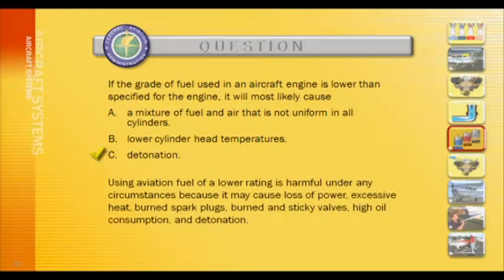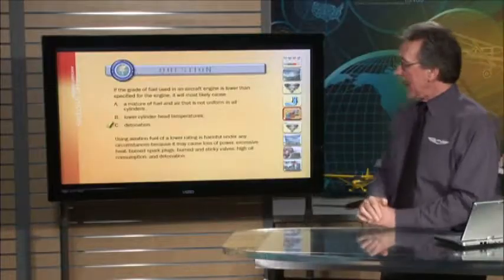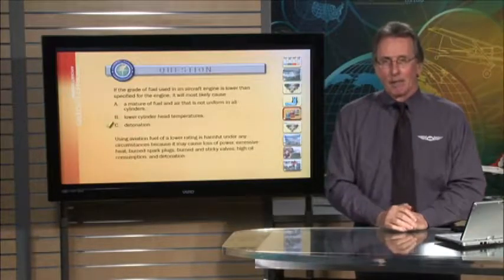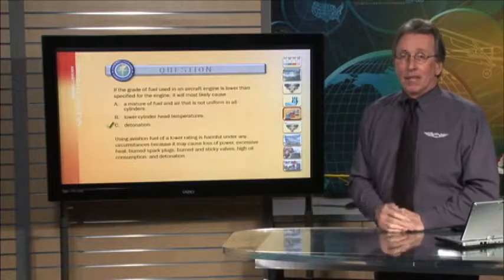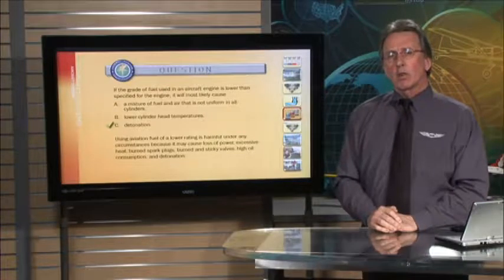A reminder here, using aviation fuel of a lower rating is harmful under any circumstances because it may cause loss of power, excessive heat, burned spark plugs, burned and sticky valves, high oil consumption, and potentially detonation. So there you have it on that topic, fuel grades. Let's move on to another topic.